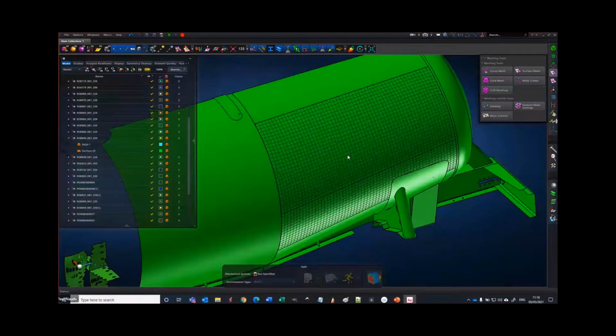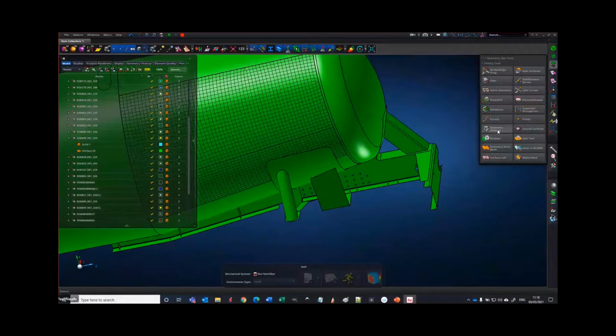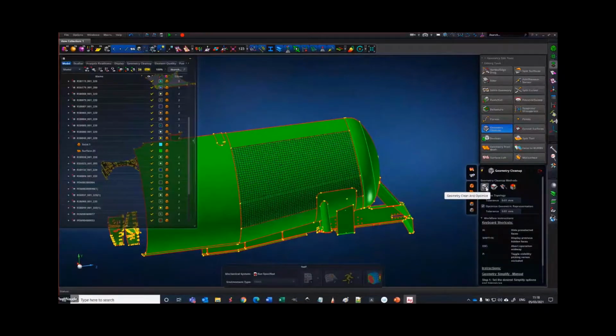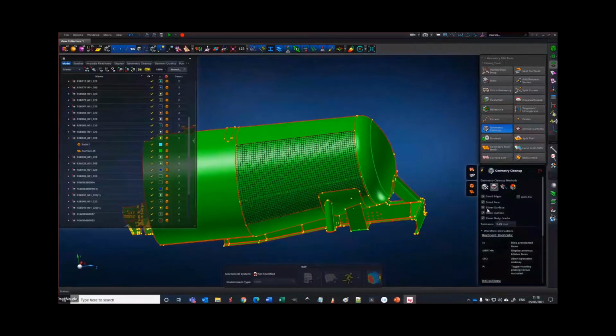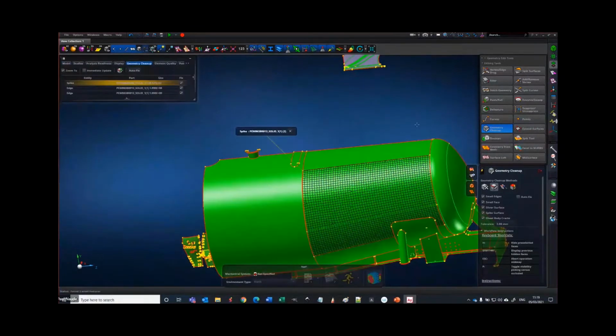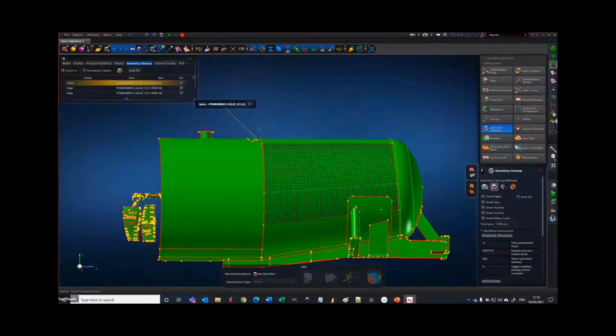When you have a lot of those, it can be a headache to find them. And this is where the CAD geometry cleanup tool comes in really handy. First of all, by just simply cleaning the CAD, you can resolve a lot of problems. But secondly, this option is of immense value. To find, let's say, anything smaller than 2 millimeters in this large model, we simply select everything that we want checked, middle mouse click, and it gives you a list of small features that are within that tolerance range. And immediately it highlights this problem area.